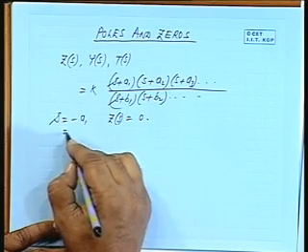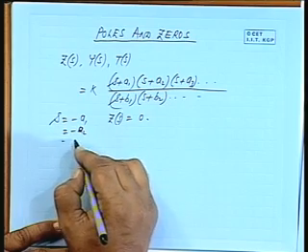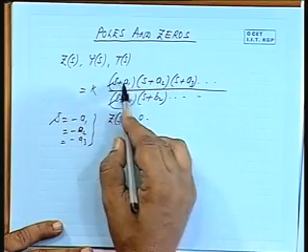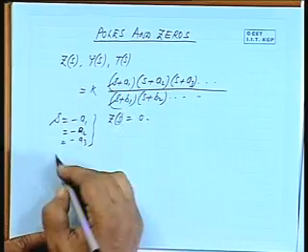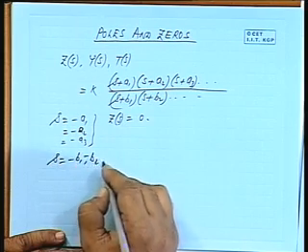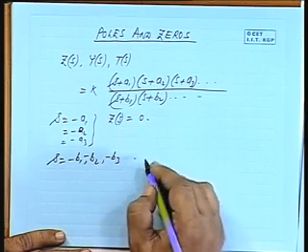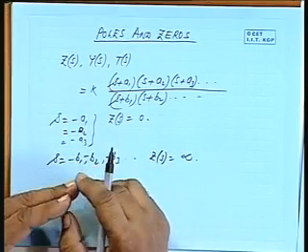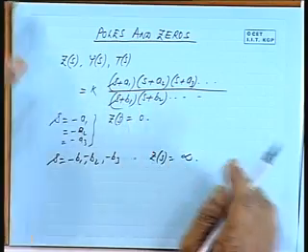Similarly, at minus a2, minus a3, zs will always be 0. If we take s equal to minus b1 or minus b2 or minus b3, then zs will be tending to infinity. So, when any function blows up, when it tends to infinity, the corresponding values of s we call them poles. When the function tends to 0, we call those roots as zeros of the function.